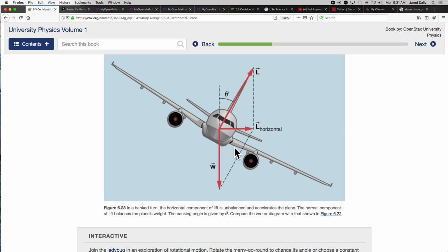It gives the plane what's called yaw, which is rotation of the plane as you're looking down on it, in that dimension. And if you have too much yaw on your plane, you can actually completely lose control of your plane. You go into what's called a flat spin, and you're almost irrecoverable, and you're going to crash. So you don't want to use your rudder to steer your plane very much. In fact, some people will just lock their rudders down and only use them a little bit here and there. But then you have your flaps as well.